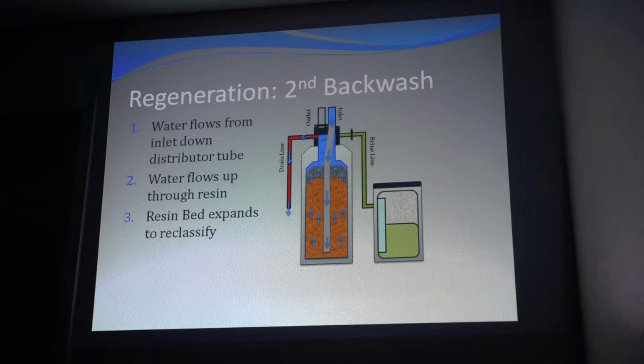Does every softener backwash twice? No. Just the ones in the boilers, or the more modern ones? The Clacks do. I don't know if the new Fleck commercial ones do. We don't use enough of them. Most of them don't. The reason Clack can do a second backwash and uses it so often, I think part of it's marketing, but they use DC drives, so their piston can go both directions.